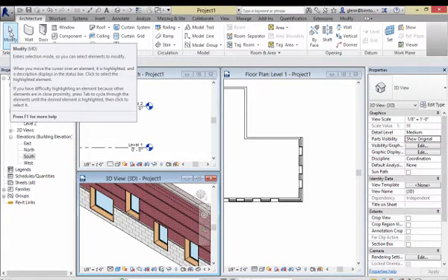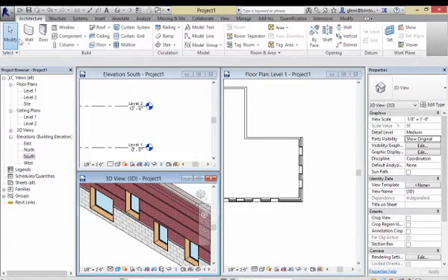Let me give you the other variation on these Revit component families. So these component families, one big thing: you have components loaded in. If you need to create a new size, some variation of the parameters, just create it, duplicate it, and go. The other thing you need to know is if fixed windows aren't what you have in mind, if you have casement windows or archtop windows, or some other geometry, something that's not just a variation in the parameters, the size, but actually some fundamental change, you can go through and load in some more.